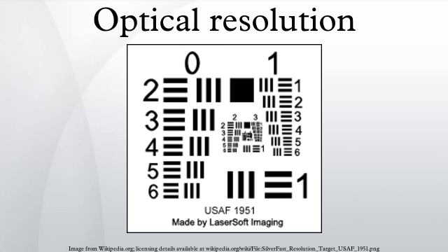EIA 1956 video resolution target: The EIA 1956 resolution target was specifically designed to be used with television systems. The gradually expanding lines near the center are marked with periodic indications of the corresponding spatial frequency. The limiting resolution may be determined by inspection. The most important measure is the limiting horizontal resolution, since the vertical resolution is typically determined by the applicable video standard.